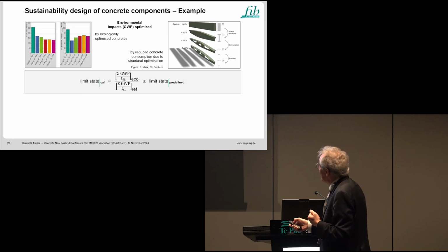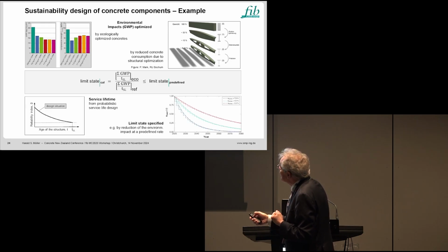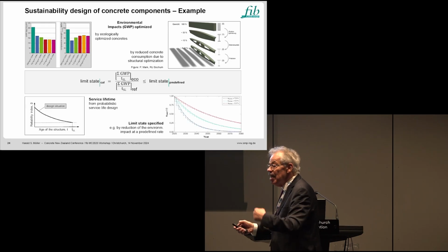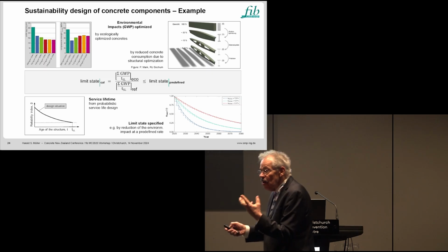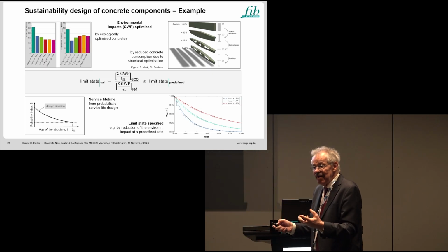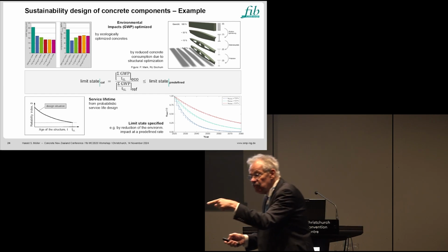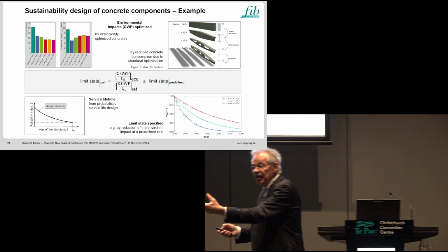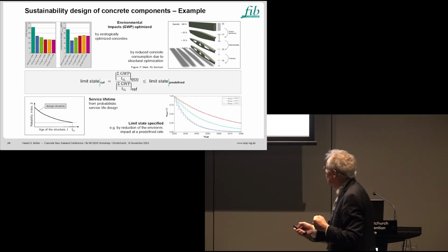Well, and then we have to look further to the service life. If we know the composition of the concrete, we can run a complete service life design. We have the formula available in its chapter, and we can calculate how the service life is. Or we can see it the other way around. You have the service life, and can look which kind of concrete complies with the desired service life.